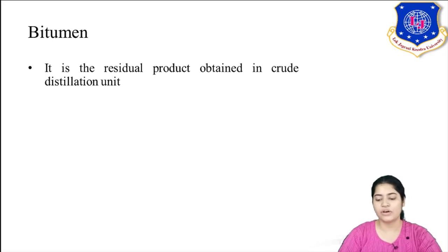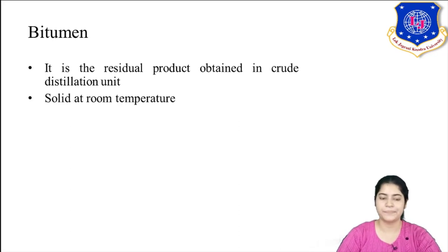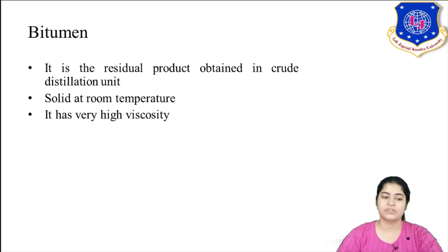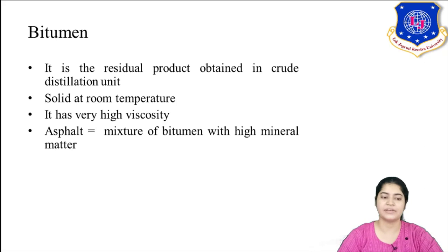It is highly rich in non-volatiles, so it is solid at room temperature. It has very high viscosity. As discussed earlier, it is the bottommost part of the crude distillation unit. Hence, it is very heavy in nature, making the viscosity very high.